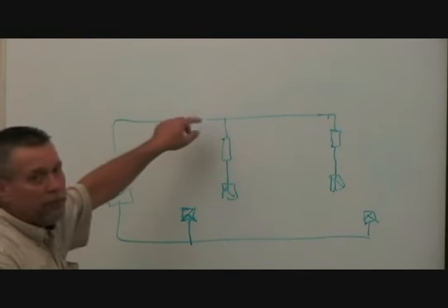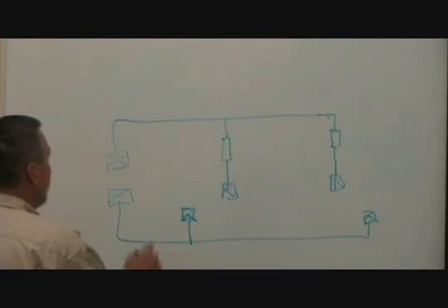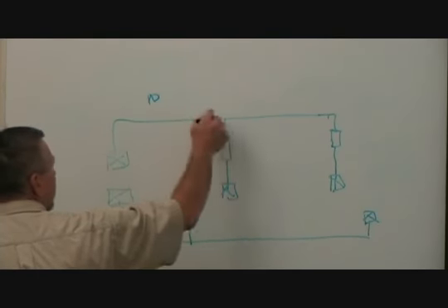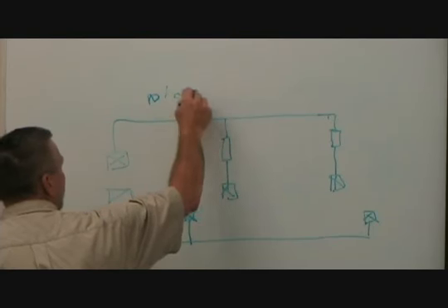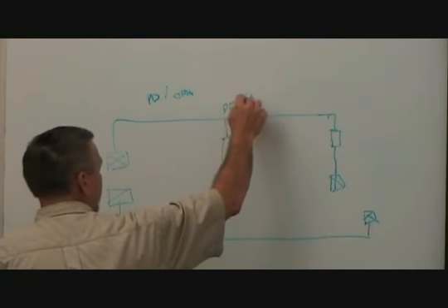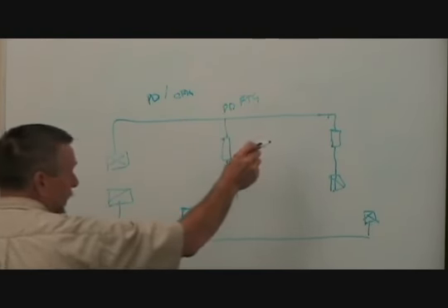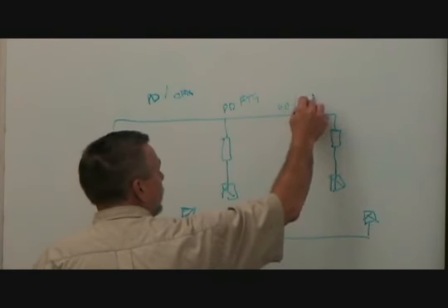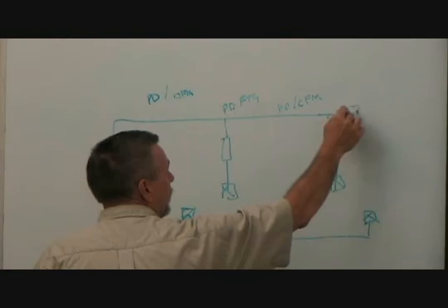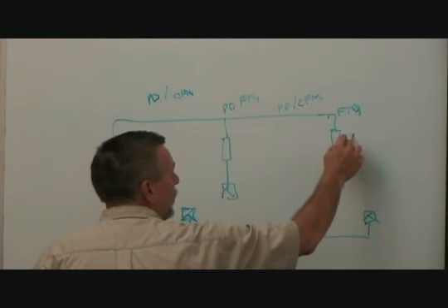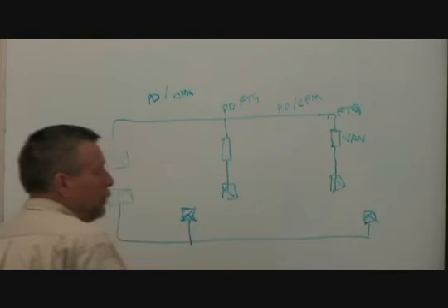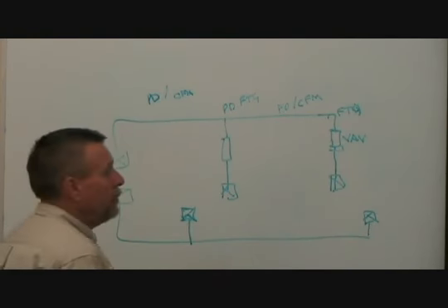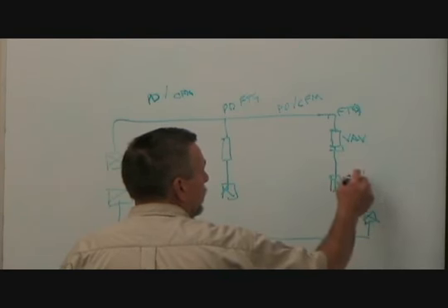You get a certain velocity and a certain pressure drop in this ductwork system. So as I was calculating the pressure drop, I would calculate the pressure drop for this string of certain CFM, pressure drop in that fitting, which is a straight through T, and pressure drop this duct based on the CFM, fittings. The VAV terminal has a certain minimum pressure drop. Generally it has a reheat coil, which is going to be your typical pressure drop, and then whatever it takes to get out to the diffuser.